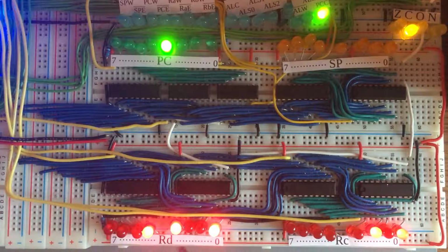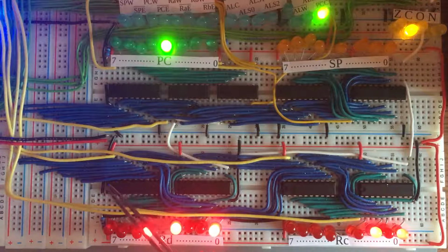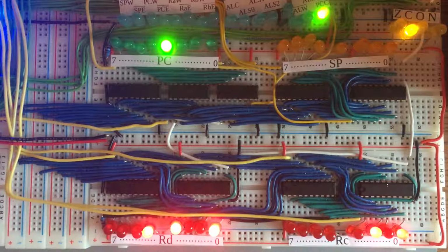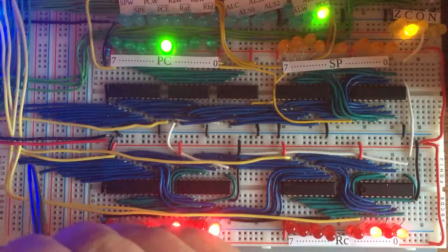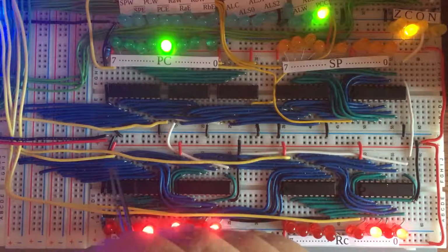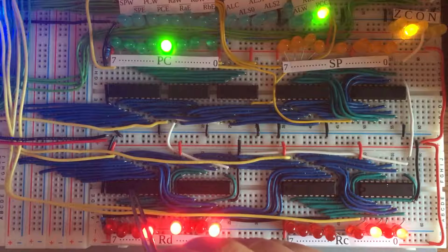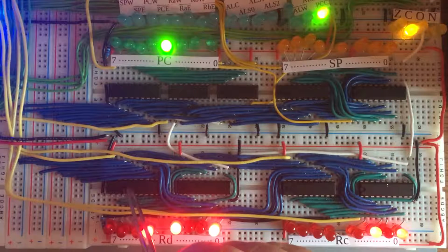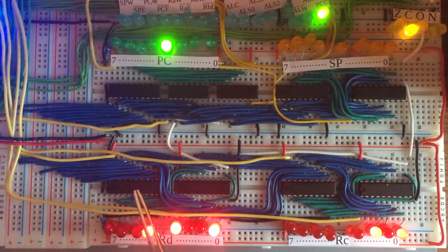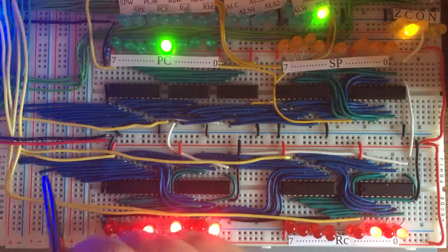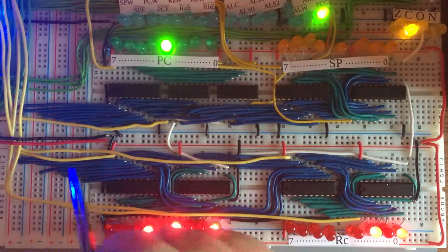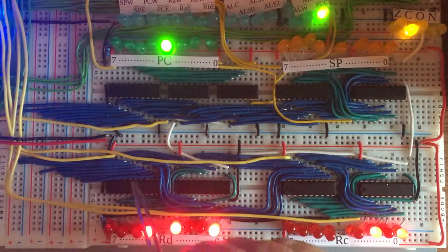And in fact, the LEDs are hooked up down the bottom here, but the actual register circuitry is basically these 2 integrated circuits up here. And so first of all, we have these blue wires which are connected to the 8 bus lines. So in fact, on the top of this chip here, which is a 74HCT245, and it performs exactly the same function as the 74LS245 in Ben's computer, these are all connected to the inputs of that chip.